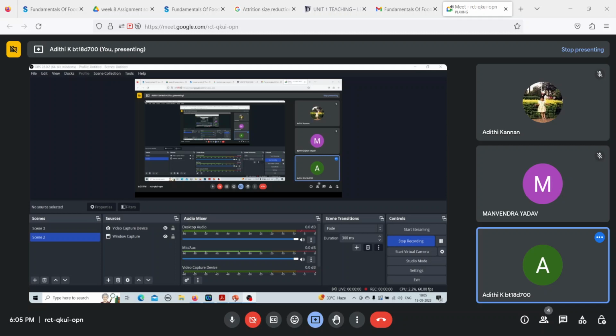In case of size reduction ratio, it becomes Kick's law. And Kick's law is used for coarse grinding and assumes m equal to 1, which is also true. And as we discussed before, Rittinger's law is for fine grinding and assumes m is equal to 2. So statement B is incorrect.